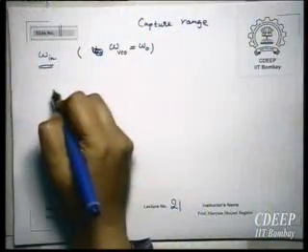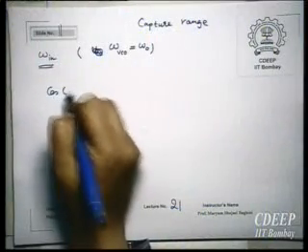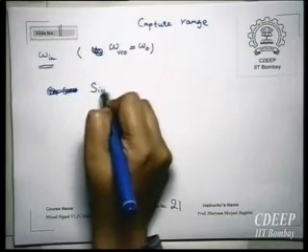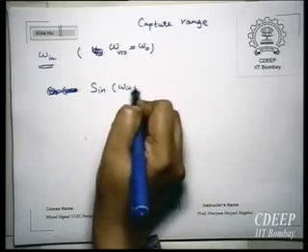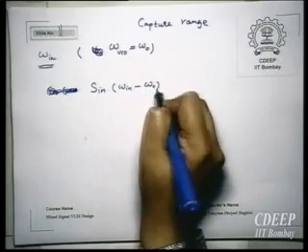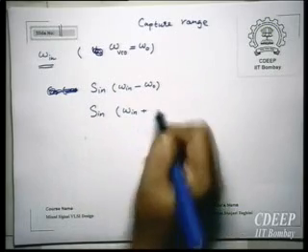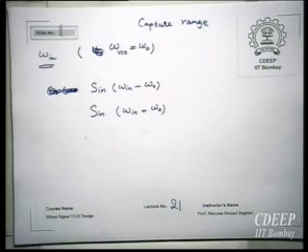Simple. So therefore at the output, you will get two terms. Right? Sine or cosine doesn't matter. So you will get omega in minus omega 0. You will get omega in plus omega 0. Okay, this is output of phase frequency detector.